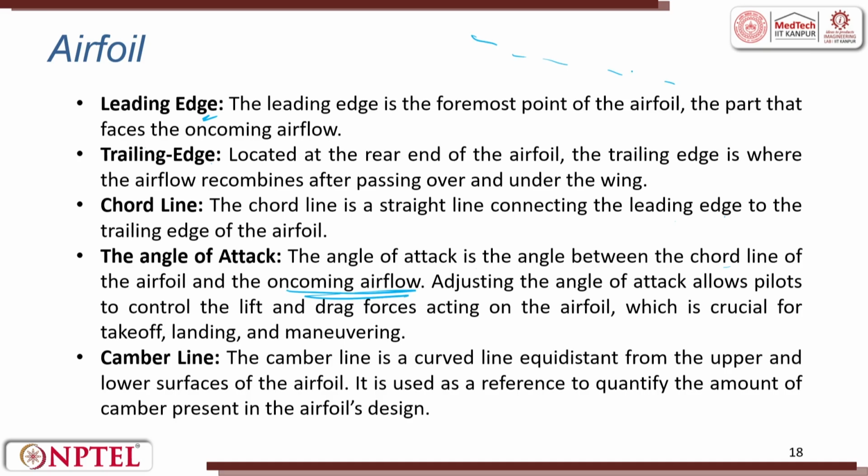So, you see a chord line like this and there is an airflow. So, this is alpha. Adjusting the angle of attack allows the pilot to control the lift and drag force acting on the aerofoil, which is crucial for takeoff, landing and maneuvering. So, they always try to talk about the angle of attack.